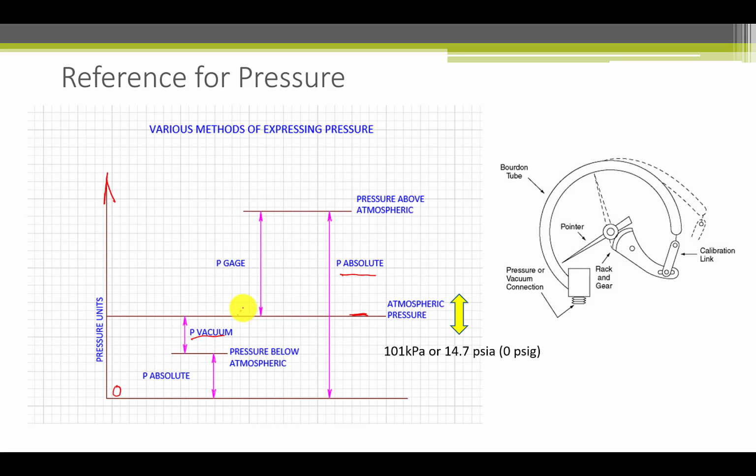So this is called pressure absolute, and when you're talking about units in the USCS system, this should be identified by PSIA for absolute. When you're talking about the gauge system, you write PSIG, for gauge. That should always be done. Of course, you don't need to add the A or the G when you're talking about differences in pressure, which is fairly common.